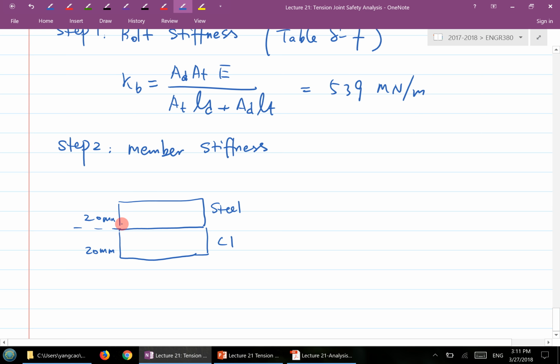Right. That's basically the member that you're talking about here. Once you finish this sketch to find the member stiffness, you draw a symmetric conical pressure shape. This sketch needs to be symmetric, but in this case it just happened because the 2 members are the same thickness, so they align with each other here. Once you sketch this properly, right?